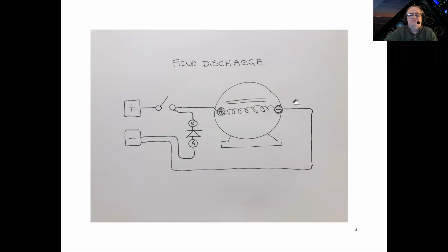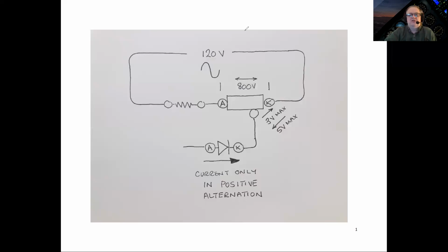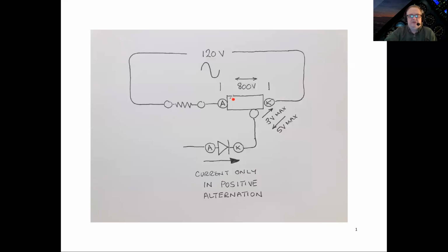All right. Now this last circuit is kind of interesting. This is something that we will be looking at a little bit later on, but let me just give you a quick introduction to what this is. This component right here is an SCR. We have the anode, the cathode, and down here, the gate. The gate, in comparison to the actual anode to cathode, has a very weak voltage rating. So the gate is not very strong.